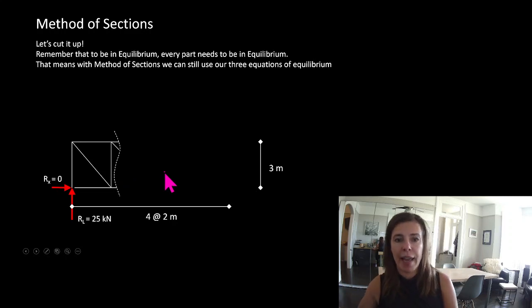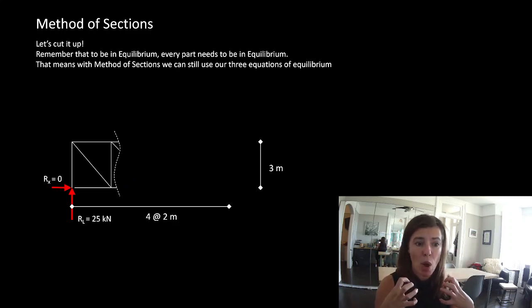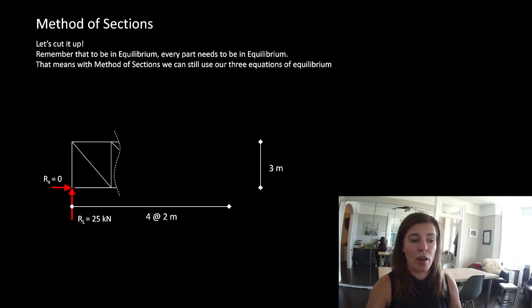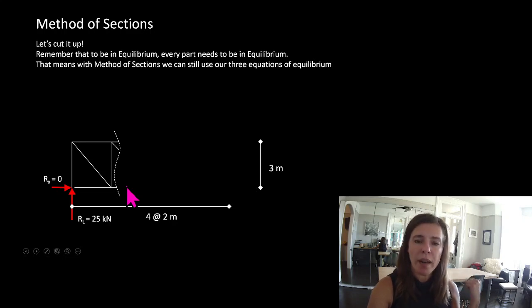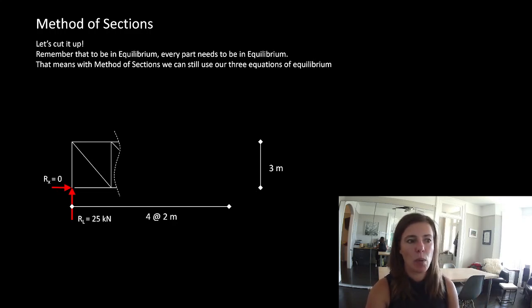My ear isn't flying off into space because it's attached to my body, and my body isn't flying off into space. So the rest of this object is what's holding it in static equilibrium. So there must be internal forces happening here that keep it in static equilibrium. But we don't know what they are. Well, it's the same way we didn't know actually what the reactions were. We figured out what the reactions were by the fact that we knew it had to be in static equilibrium.